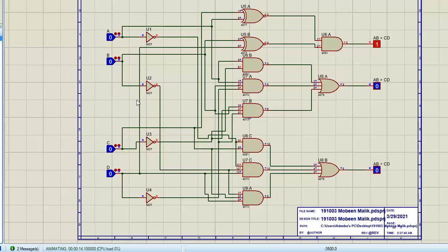If I talk about the demonstration, right now this number is 0 and this number is also 0, which shows that 0 is equal to 0, and here the logic probe with the equality sign is showing that these 2 numbers are equal. If I make the number 1 greater than the number 2 and do it like this, we can see that the greater probe is on.